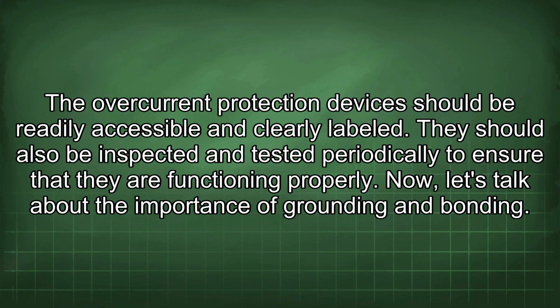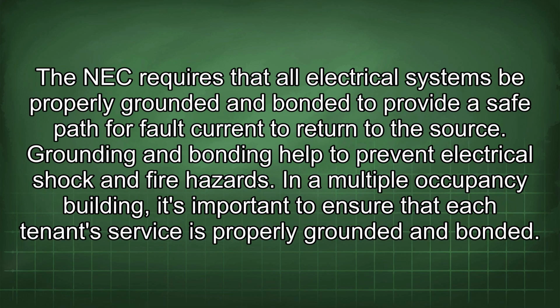Now, let's talk about the importance of grounding and bonding. The NEC requires that all electrical systems be properly grounded and bonded to provide a safe path for fault current to return to the source. Grounding and bonding help to prevent electrical shock and fire hazards. In a multiple occupancy building, it's important to ensure that each tenant's service is properly grounded and bonded.